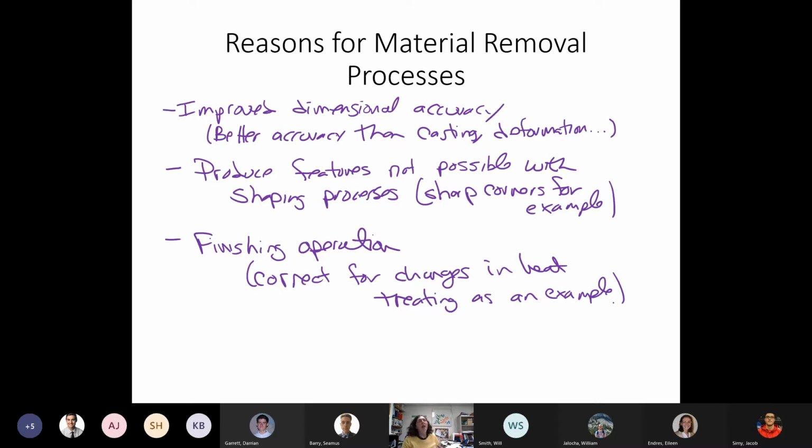One area that we really haven't discussed, well, it might have been mentioned in 321 or 322, is the dimensional changes that we get when we do heat treating. If you have a part and you heat it up, you're going to have thermal expansion, and that thermal expansion is maybe uniform on the heating, but certainly on the cooling, it's not going to be.